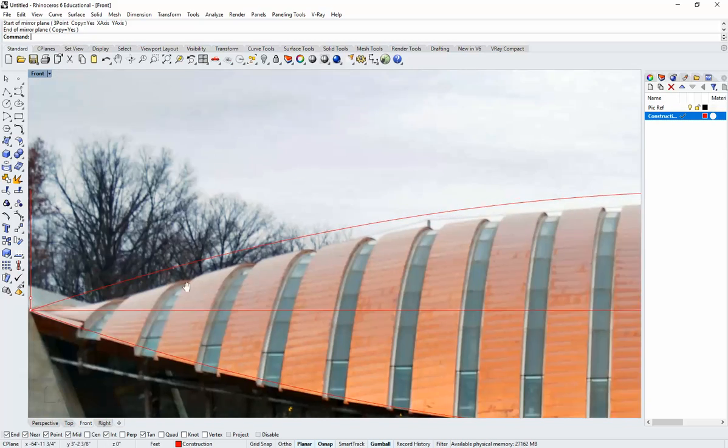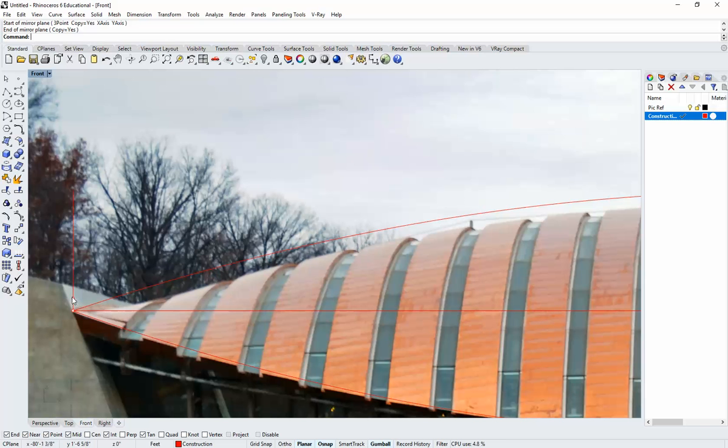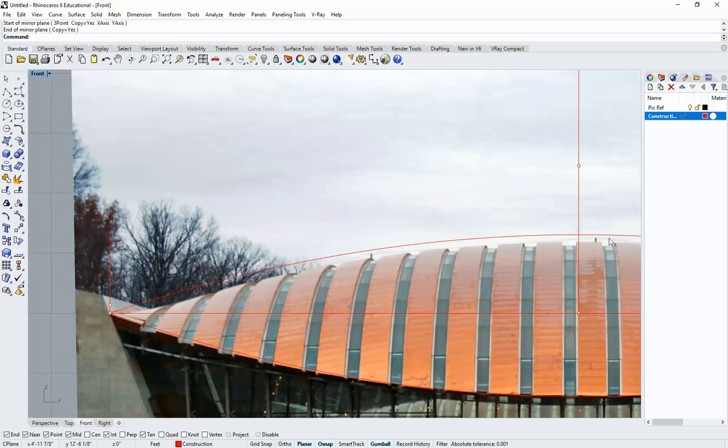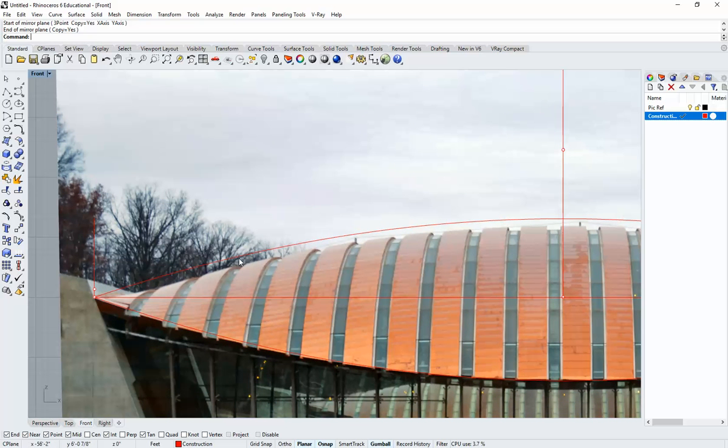I'm going to use that point now to set a tangent from this point tangentially to that curve, because I don't really like the way it's ending. We have a nice sweeping curve up here, but then it gets a little bit maybe too high along this end. It looks like it goes a little straighter, and then it starts to curve. So to get a little bit more accurate with it, instead of using control points for that, I'm going to use a tangent line, and I'm going to trim it so that it starts curved and then ends up straight coming to that point.